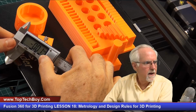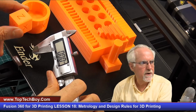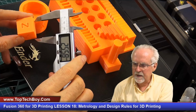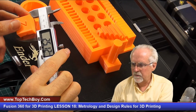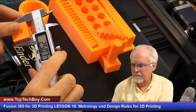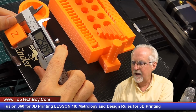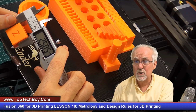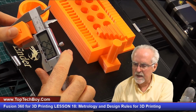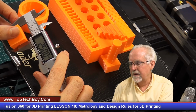So I'm going to come in, I'm going to zero this out, and then remember we designed this to be 25 millimeters by 25 millimeters by 25 millimeters. I'm going to get this and make a measurement. And you can see that that is 25. I wanted 25 millimeters. It is 25.04. That is really pretty amazing, right at 25.